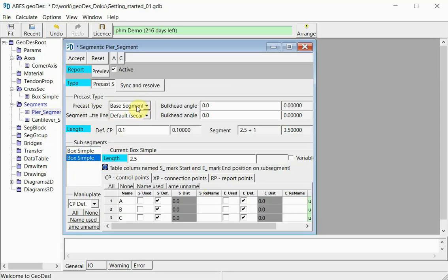And because we are on such a tight corner, such a tight radius in plan view, I think it makes sense to put the pier segment as a tangent onto this axis, so that the bearings, both bearings, are on equal distances from the axis when we build the bridge. So I'm choosing a tangent here as my rule to place this segment. Then that means that the start and the end of my full pier segment will be slightly offset laterally to this curve of our axis.